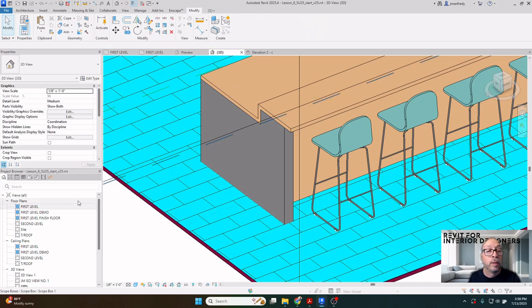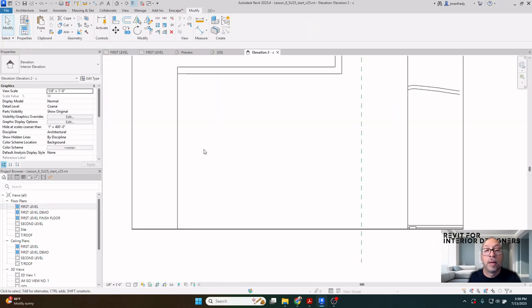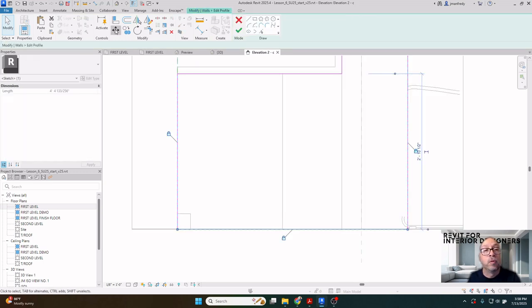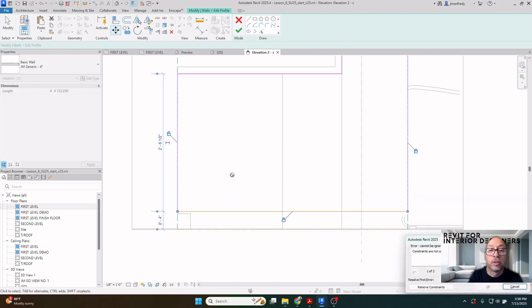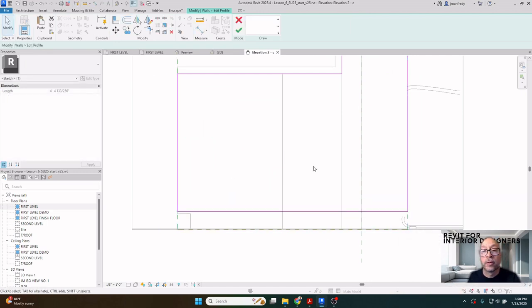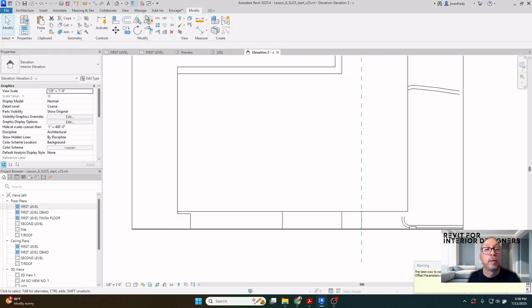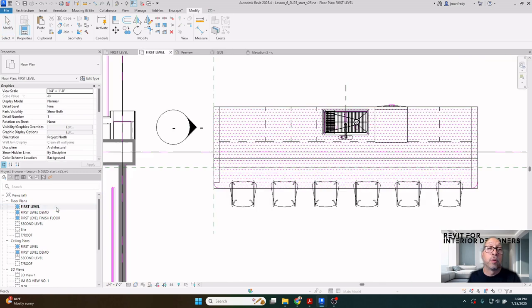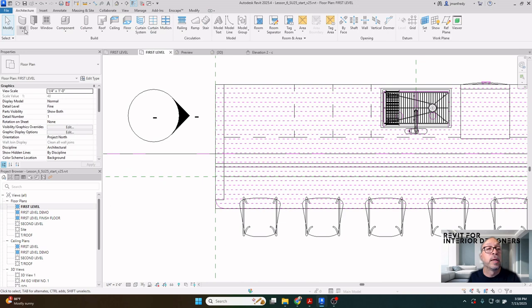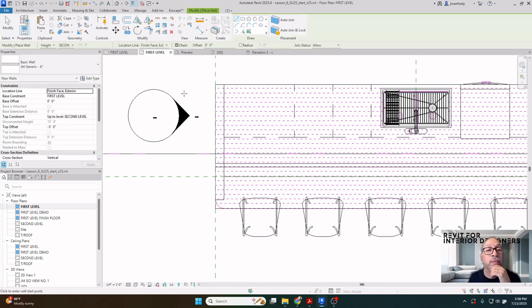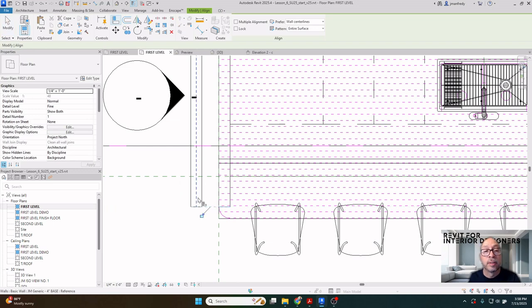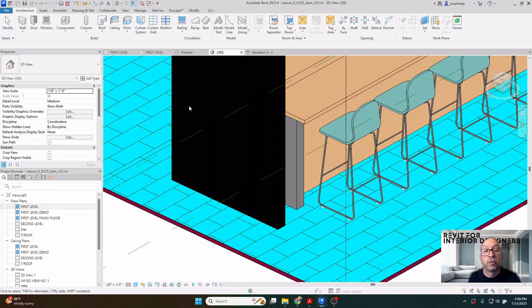There's a normal wall here. So in here, I will simply grab this wall, edit the profile, grab the bottom, use the move command and point straight up 4 inches. Remove the constraints. Hit OK. And then you'll see here that the wall is now 4 inches shorter. Then I will make another wall, except the next wall I'll build here in plan view is the one with the base. I'll draw it here next to it. I'll maybe use a line command to make sure they're lined up nicely. They're the same length. I'll draw it there next to it.